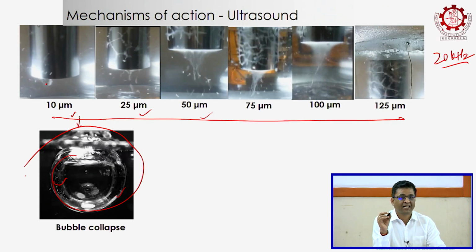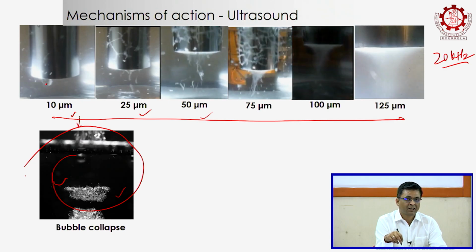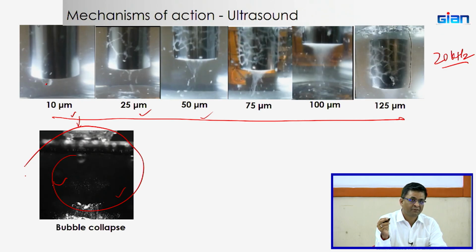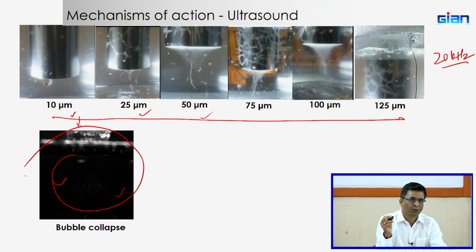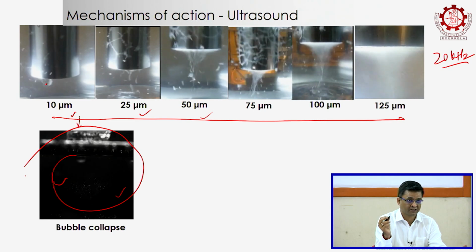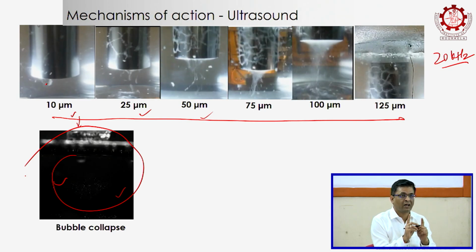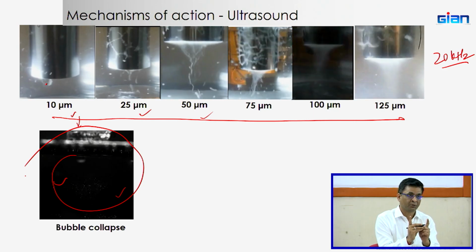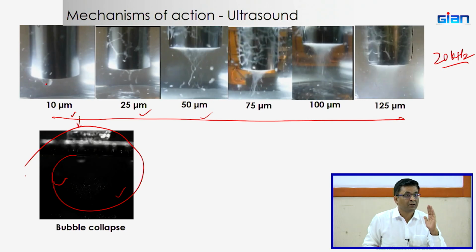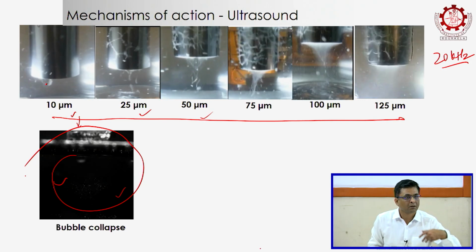It makes a really loud noise. When you are using an ultrasonic of, suppose, 750 watts, and you really want to use the full 750 watts, take that ultrasonic probe and put it into wood, or any hard surface. Ultrasound will always try to vibrate at the same amplitude. If it doesn't get enough room to vibrate, it will use the full power, and if it's not able to use full power, it will be gone.